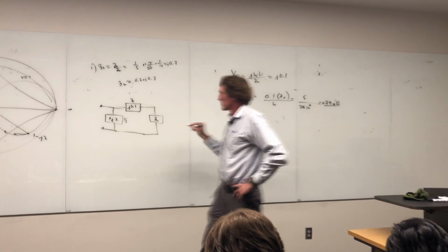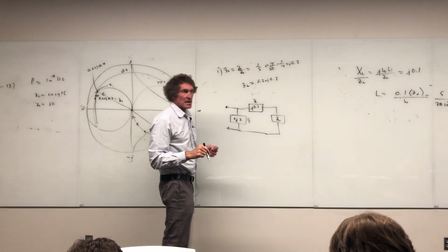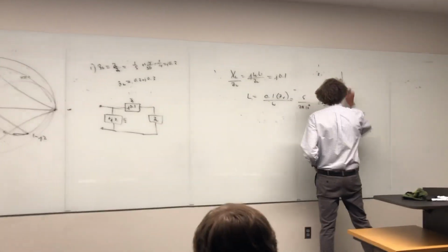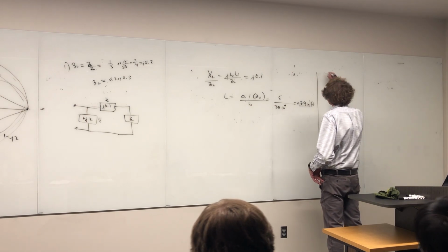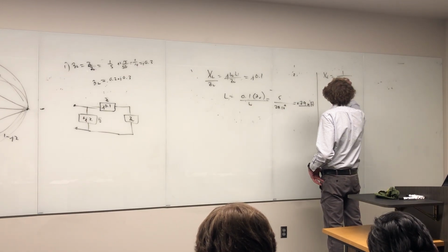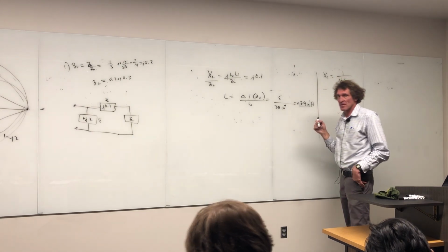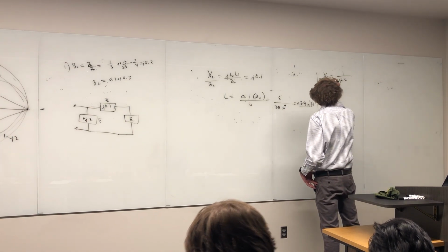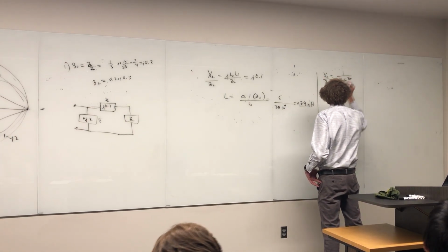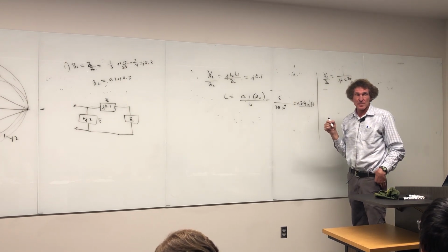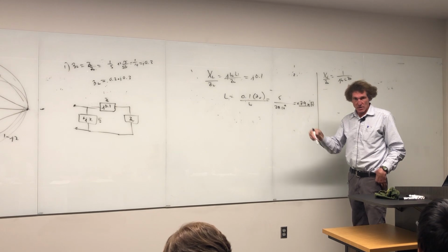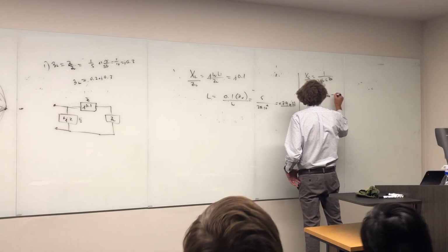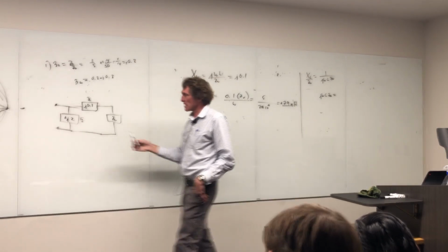Now for the second one, it's going to be a capacitor, right? I'm going to bore you with this, but I do this for a reason. If you get it down, you don't mess it up. First, the impedance of the capacitor is 1 over j omega C. Just start there. You know the impedance. That's why I always go this route. Then I normalize it. Now I have the normalized impedance. Since we're in the admittance domain, I take 1 over that. 1 over that means I have j omega C times Z naught. Now that's normalized admittance, and it's got to be equal to j2.